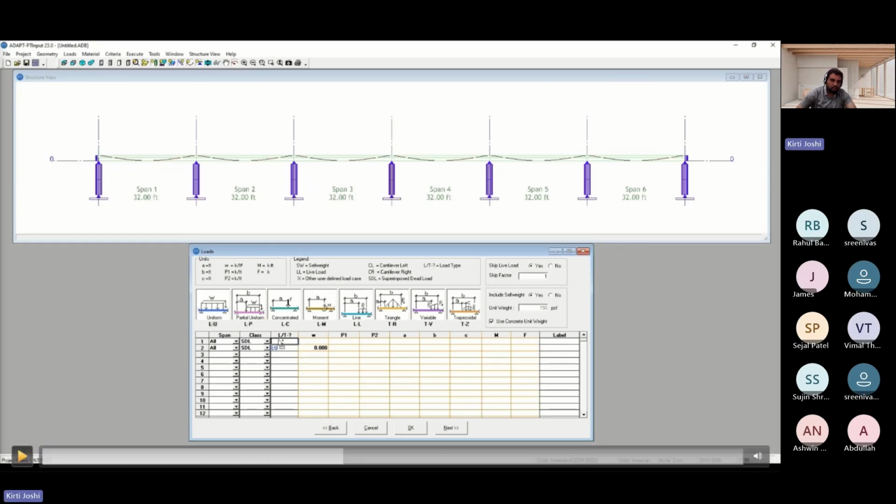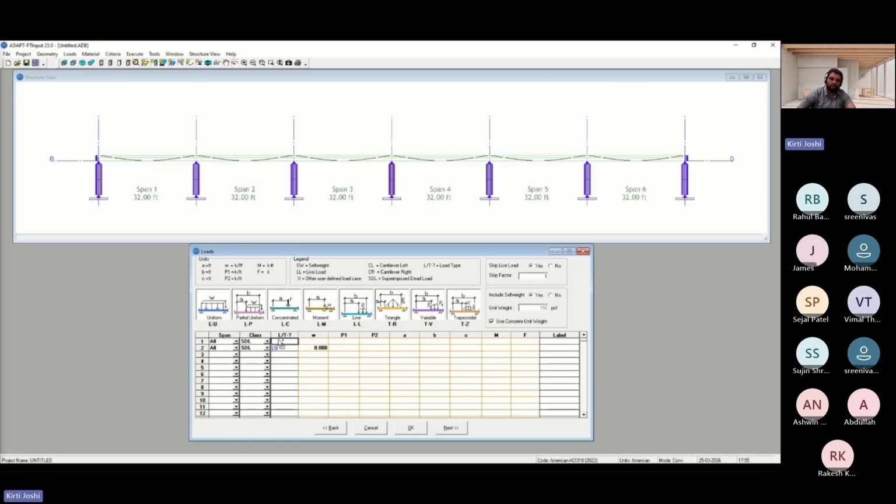You can see there are the uniform load, the partial uniform, and the concentrated load options. One way is to simply drag any of them into the required rows. Otherwise, you can simply type the letter; U is for uniform, so you can simply type U within the rows, and it will be assigned as a uniform load.